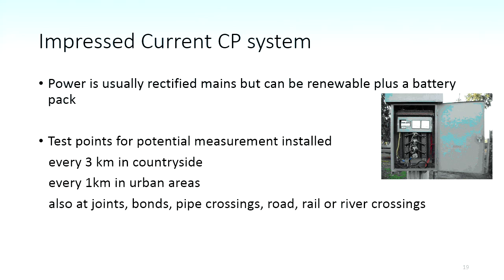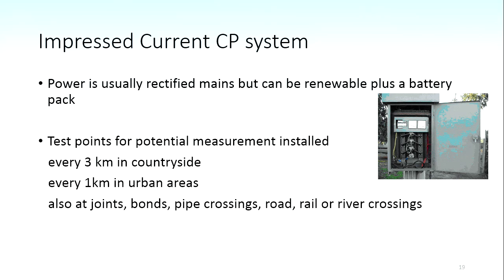So anywhere where there's likely to be stray currents from other CP systems, from electric trains, from where there are changes in water table level, etc. So test points are useful things in the design to check the potential on the pipe.